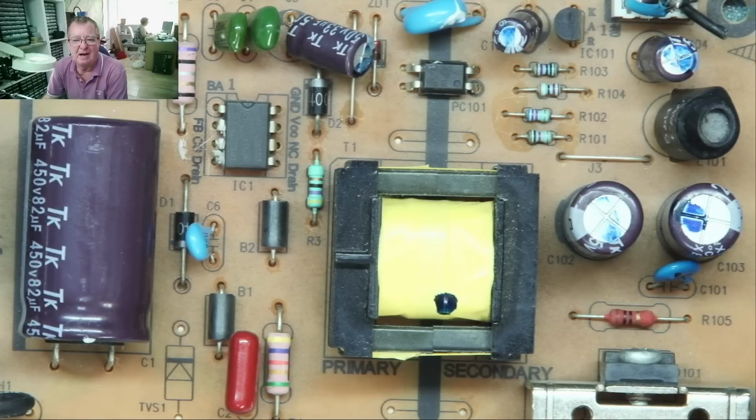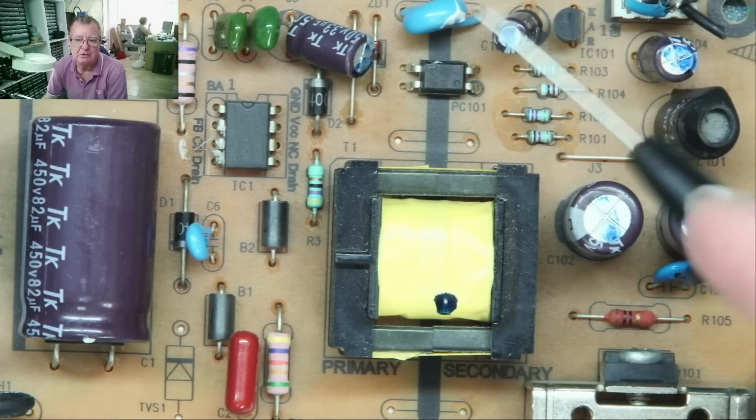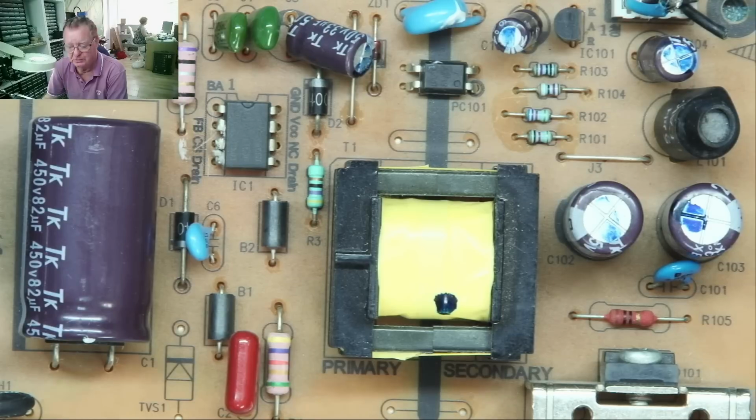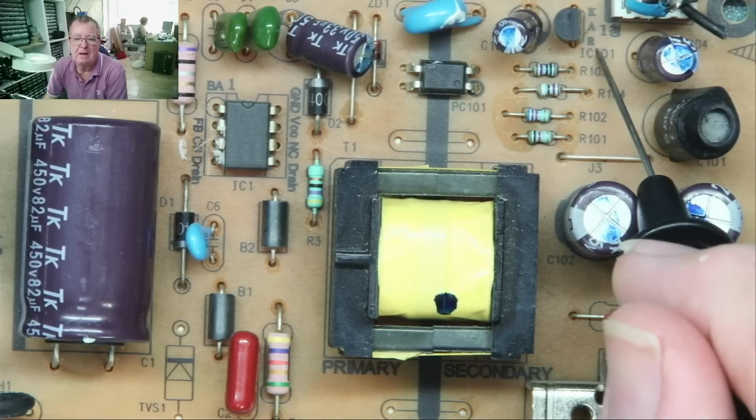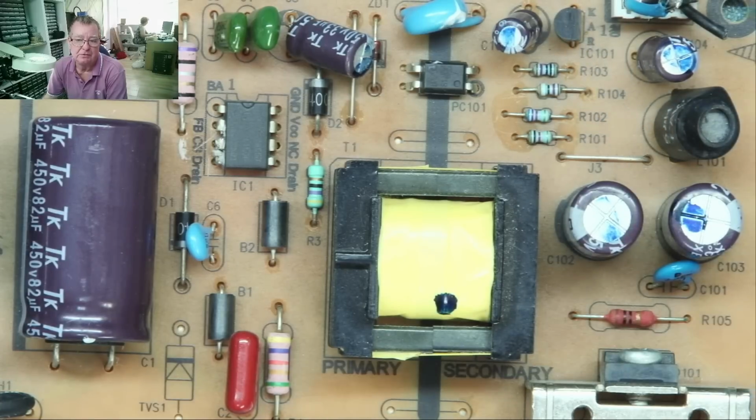So a Zener diode, which we'll just talk about briefly in case you're not so familiar with them, is a type of diode that is used as a voltage reference that will have a certain voltage across it which is stable whenever the supply voltage is higher than the Zener voltage. So if you have a 12 volt Zener, and you put more than 12 volts across it, the Zener diode will maintain the 12 volts. This does exactly the same thing. It's just programmable. By putting the voltage on the reference pin, you can change the Zener voltage.